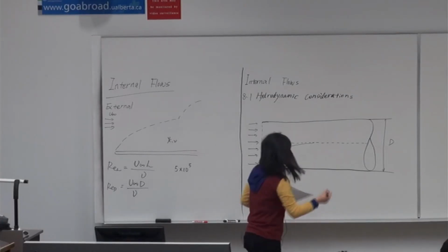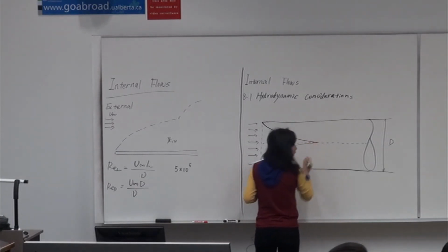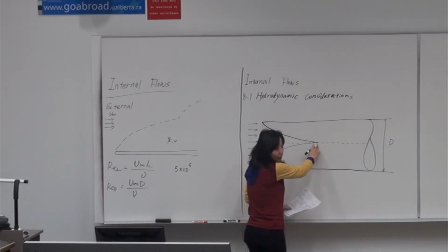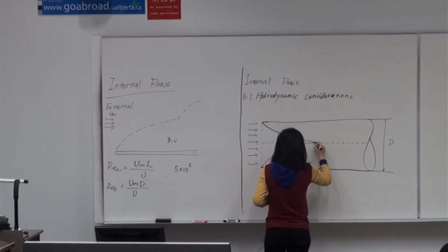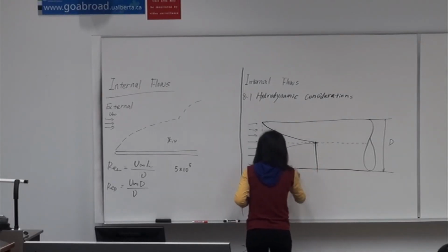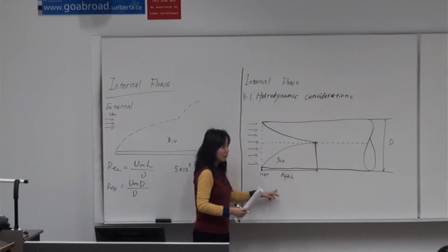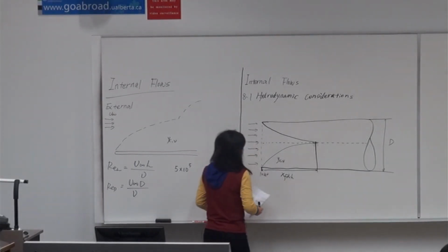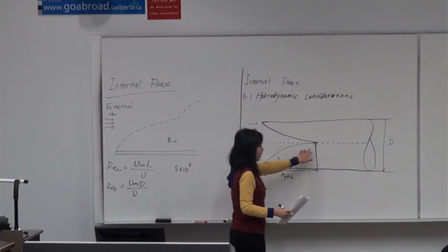Now the two boundary layers, which are the same by symmetry, gradually merge at the center line, and we term this point x_FDH. That's a notation given by the textbook, which is the fully developed hydrodynamic entry length. Once the velocity boundary layers collide with each other,